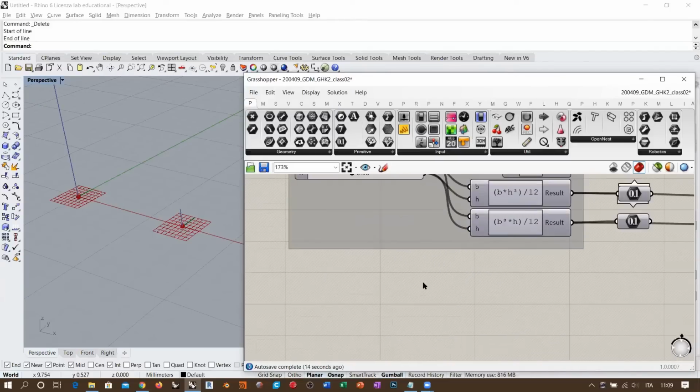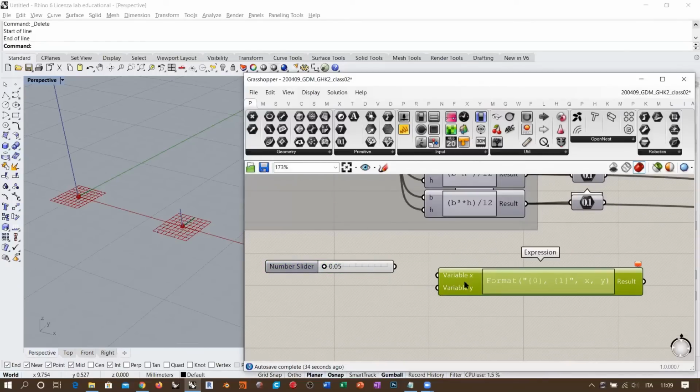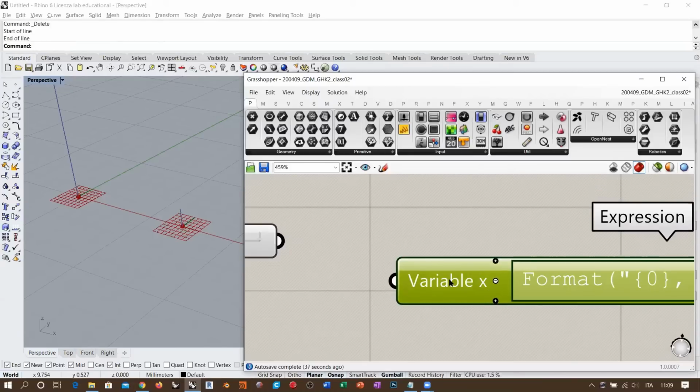And then I might have, for example, a circular cross section. So in that case, eventually, I would define a radius parametrically, because I want the radius to be something between, I don't know, 5 centimeters up to 50 centimeters. So something very thick eventually. And then I create an expression here, getting rid of the variable y.